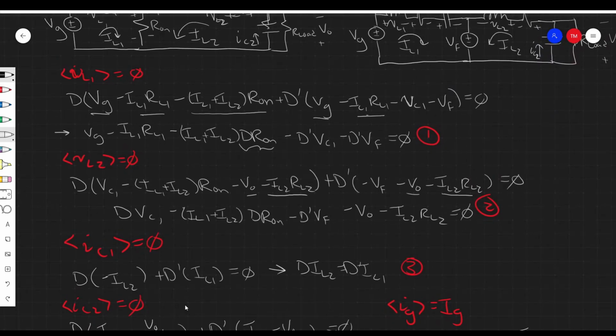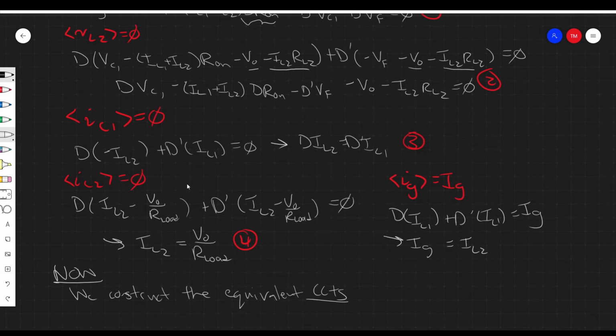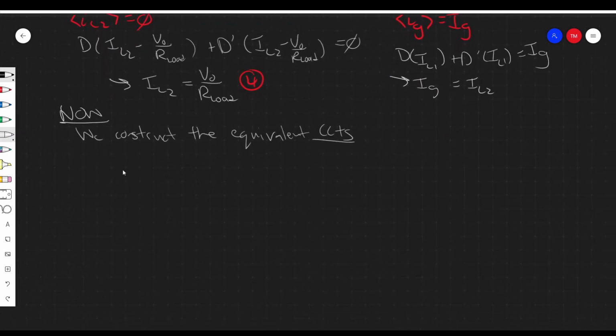So this first equation, equation 1, represents the inductor current loop. So what we can do is imagine that for equation 1, we have an imaginary inductor, right? An imaginary inductor L1. I say it's imaginary because this whole idea of DC modeling is basically to eliminate the inductor, right? Or eliminate the dynamics of the inductor. We're just looking at the DC components. So it's there. I'm drawing it there because this is what this loop represents. We can imagine that this loop carries the inductor current IL1, right? But its effect isn't really there, right?